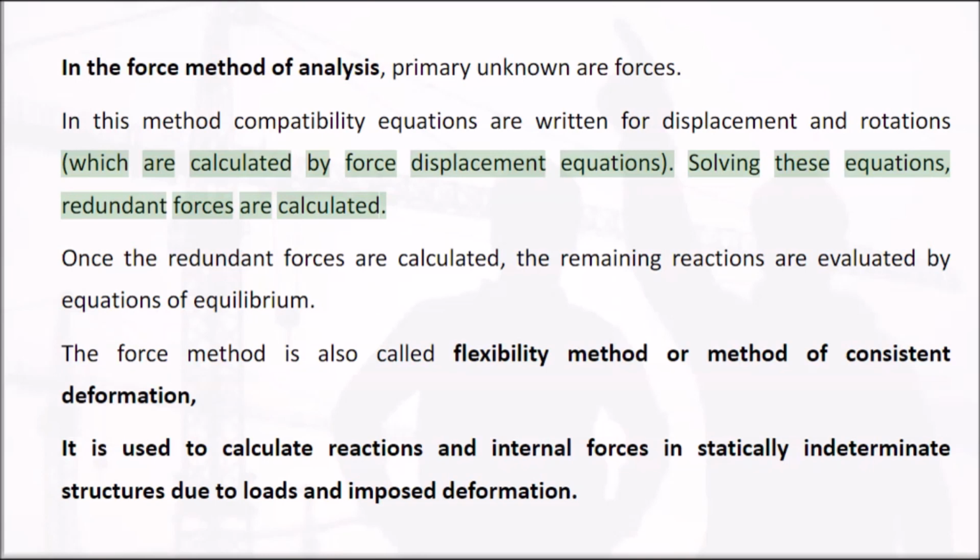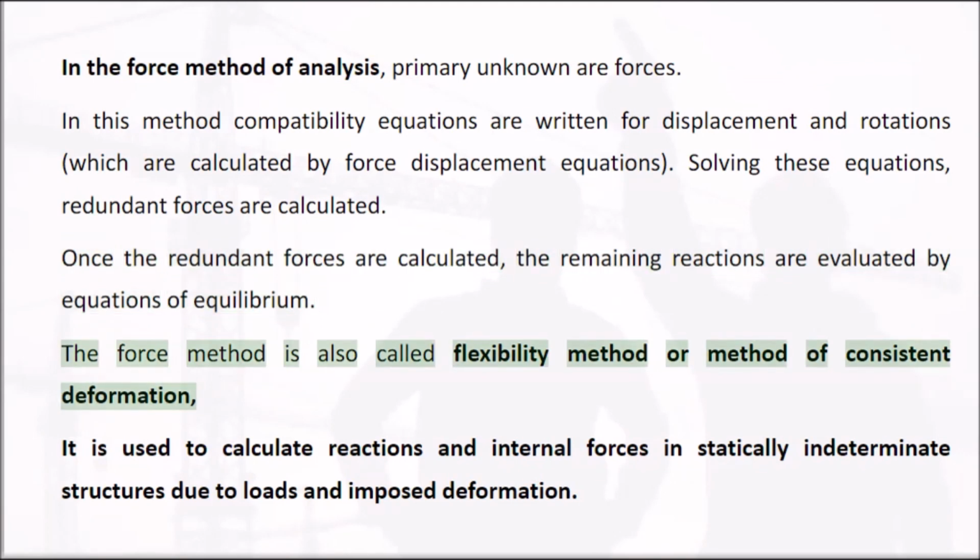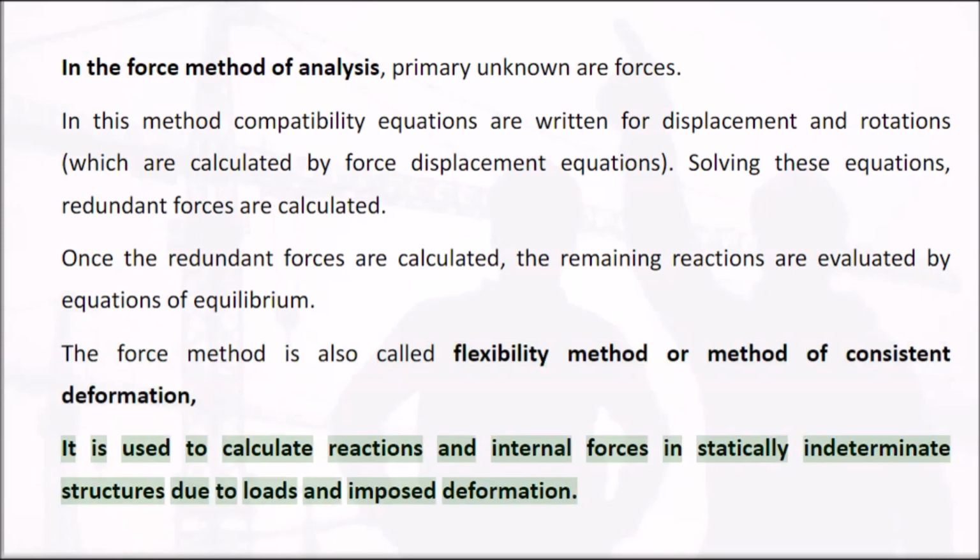Solving these equations, redundant forces are calculated. Once the redundant forces are calculated, the remaining reactions are evaluated by equations of equilibrium. The force method is also called flexibility method or method of consistent deformation. It is used to calculate reactions and internal forces in statically indeterminate structures due to loads and imposed deformation.